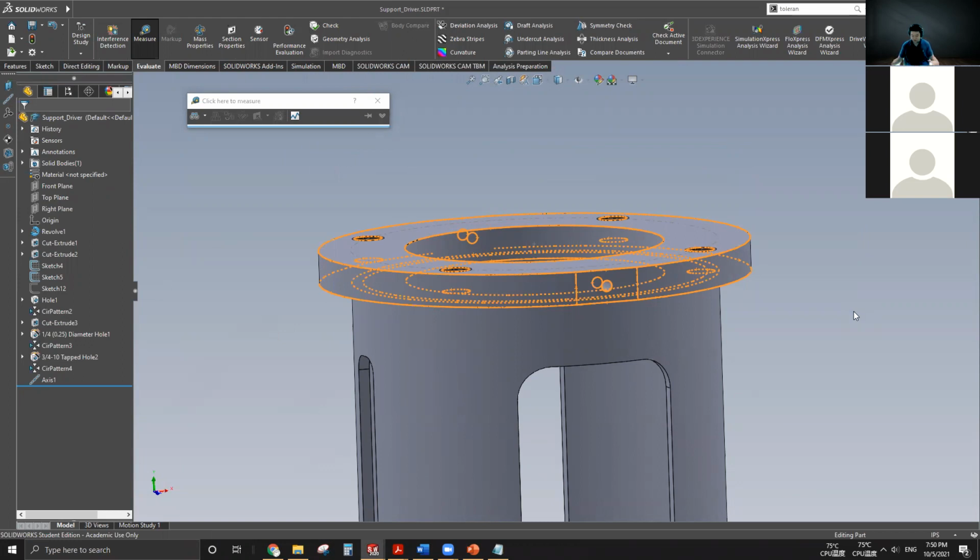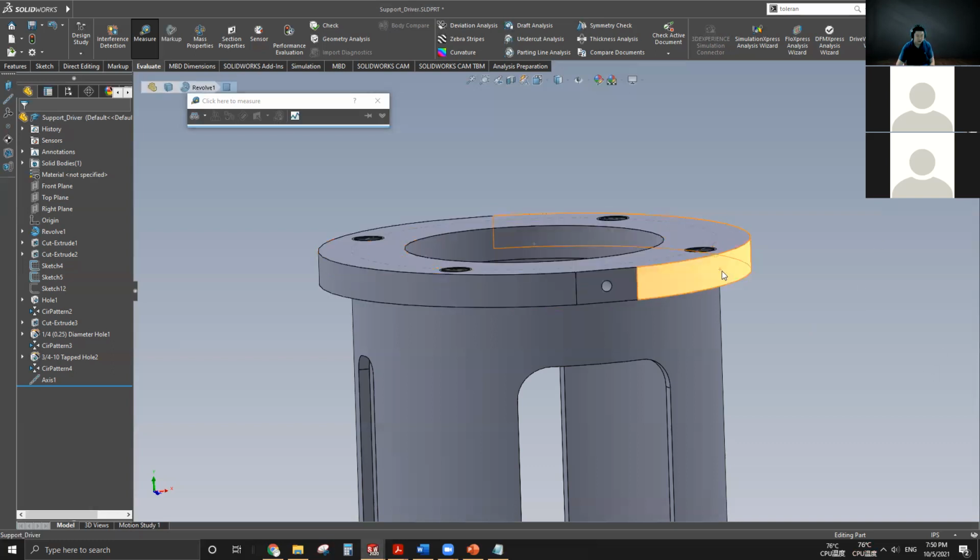You need to fix this plate on a milling machine first, right? And how to fix it? You either have a clamp, or you have a block to squeeze it so it doesn't move at all, right? So one of the datums to fix this plate should be the outer surface, right?